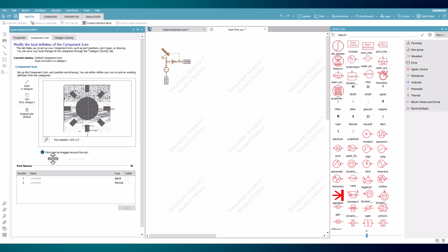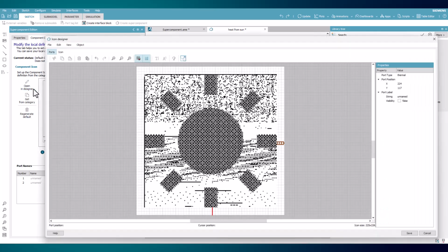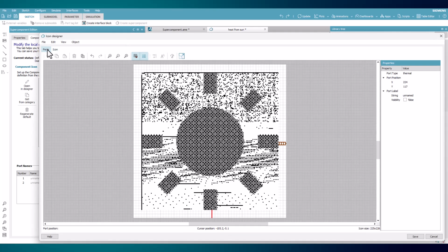The display shows the current component icon. Opening the Designer tool, there are two options available. Ports is selected first and allows the user to have their position changed around the edge of the available canvas, which is what is displayed for the icon. The options available from the ribbon above include zooming in and out, fitting the canvas to the screen, having shapes snap into a particular position, and to disable or enable the grid.